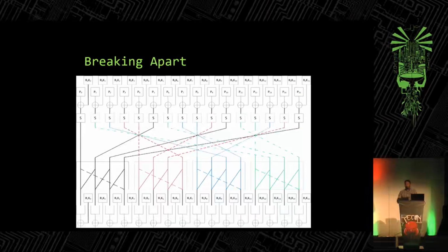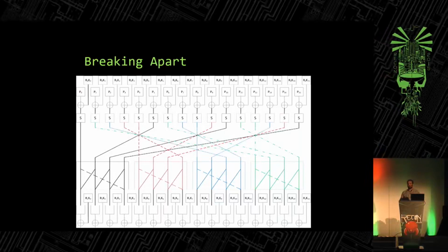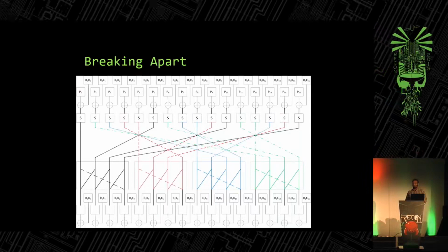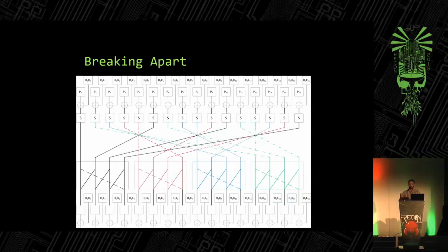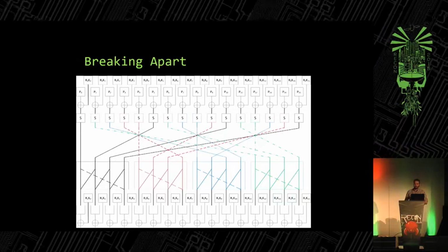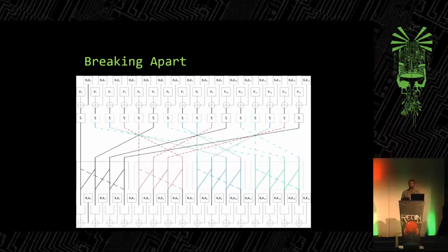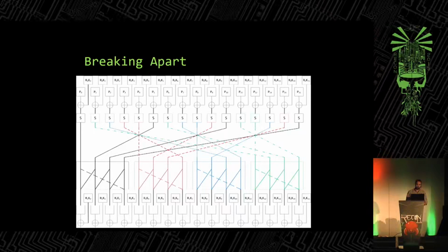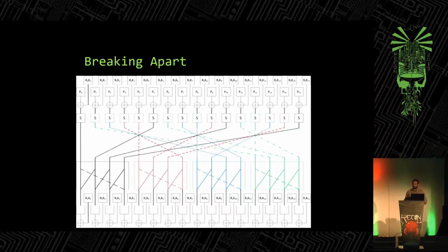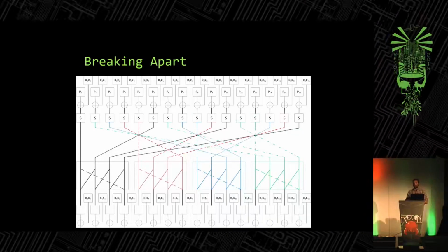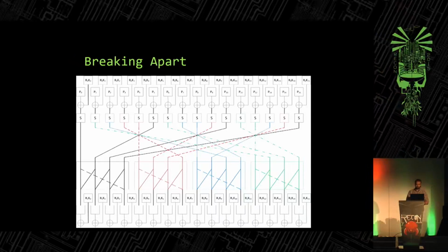So we're only looking at 1 byte of the key, and the output at that one spot. We could figure out, based on the power analysis, that there were 4 bits set when I put in a plaintext of hex AB. And the only way we get 4 bits set is if the key is some other byte. In reality, we'll get a candidate number of possible bytes for that key. So we could send in another piece of plaintext, and there is 2 bits set at that intermediate value. We know how the algorithm works, so we can narrow down what that byte of the key is. So we're doing this guess and check on a single byte of the key, and we just do it 16 times in a row. So it's just 2 to the 8 guesses, 16 times. So it's a very tractable and easy amount.